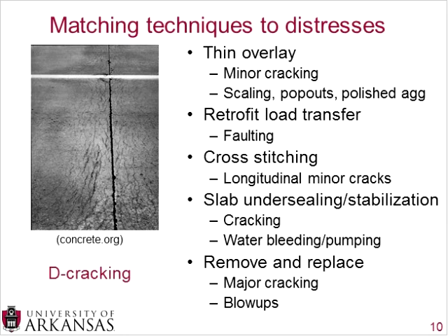A very common thing you see, in fact, if you ever drive on Highway 412 in eastern Oklahoma, you'll see that they had to retrofit load transfer, and this will prevent faulting or future faulting. This is a very distinct technique because at every single joint you will see 3 narrow bands of concrete that has been replaced, and that's because you need to actually take material out at each joint, place a dowel bar down into there, and refill that small slot with new material. So it's a very distinct technique that's pretty easy to see.